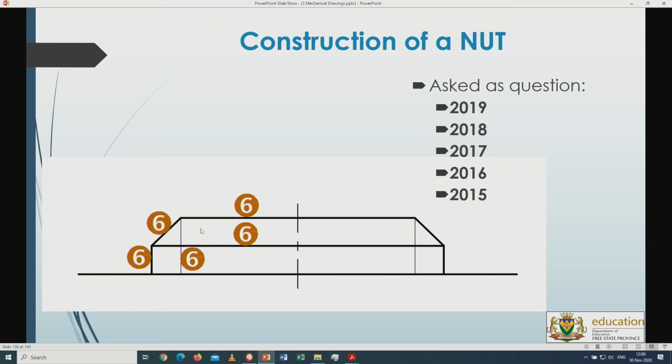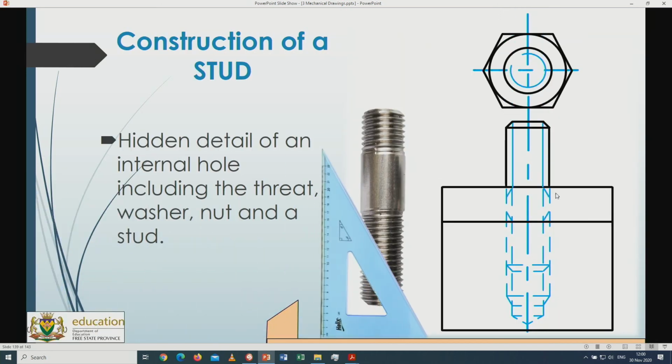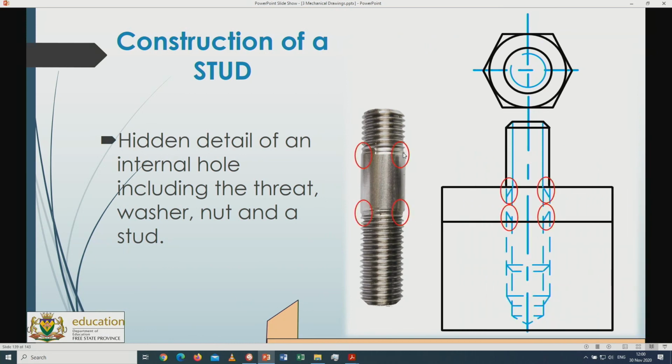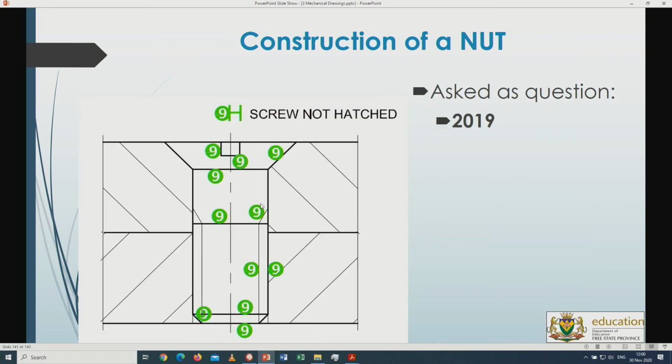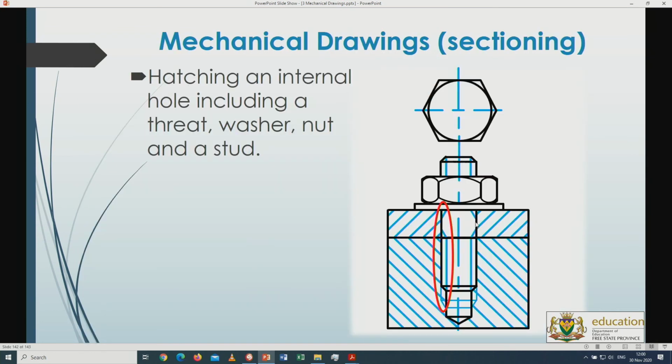Nuts and bolts and top ends, it's always important to indicate. So that's my 60 degree for my die. That is basically cutting the thread in here, and then yes, seen from above, solid on the outside, broken circle on the inside. Then over here again, 45 degrees, the distance over there, 60 degrees, solid line, and then the examiner gave this information to draw this upper part over here, which was asked in 2019.